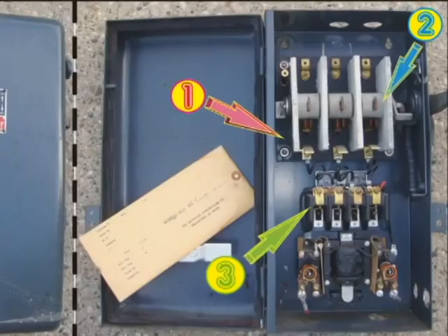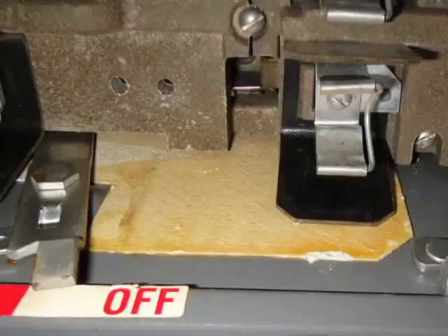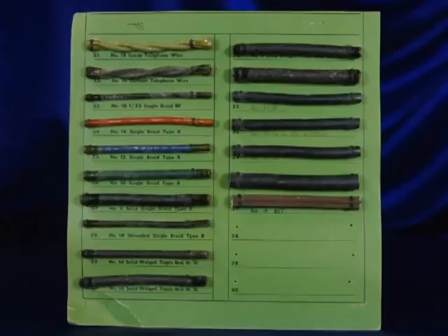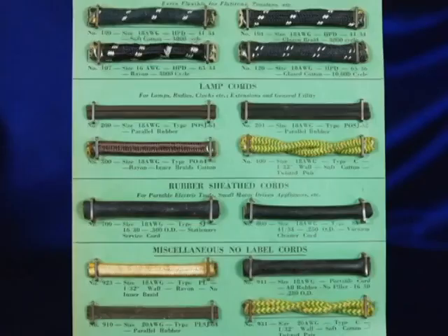Here's an example of an electrical fuse box. You can see the paper back behind the fuse block itself there. That paper would be considered a friable material. The cloth on the wiring, if it was brand new and in good condition, would be a category 2 non-friable, but if it's really deteriorated, really old, chances are it should be handled as a regulated material. If you're ever working around electrical fuse boxes or switches or anything, make sure they're de-energized before you even get up close and personal to them.